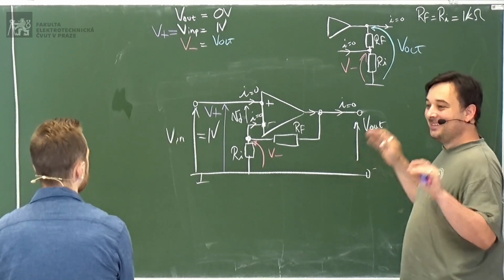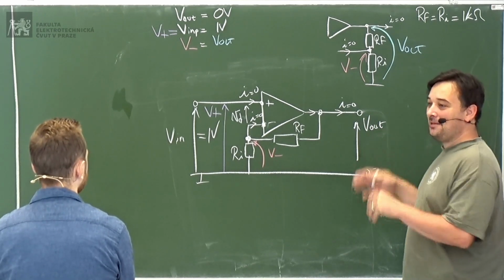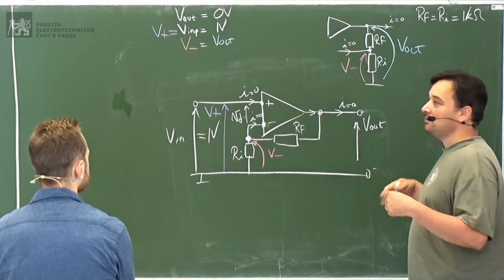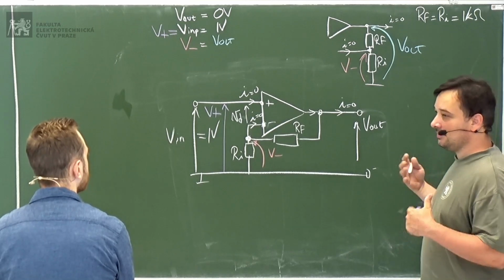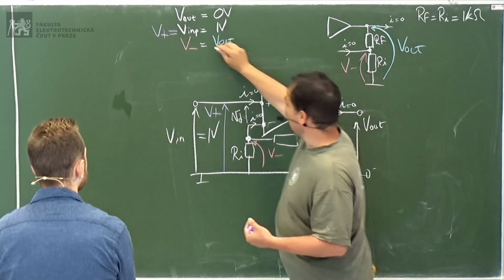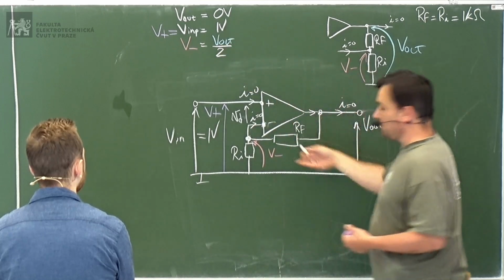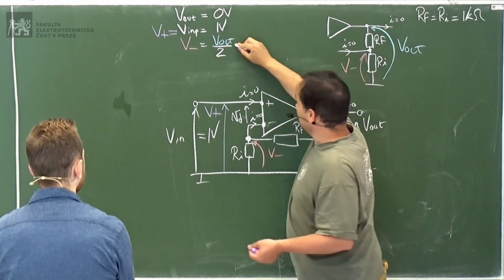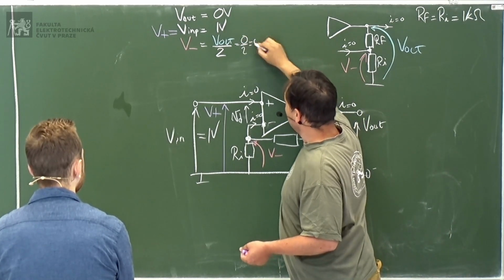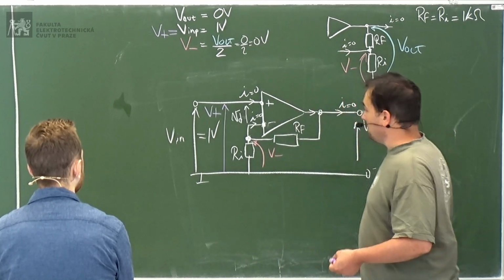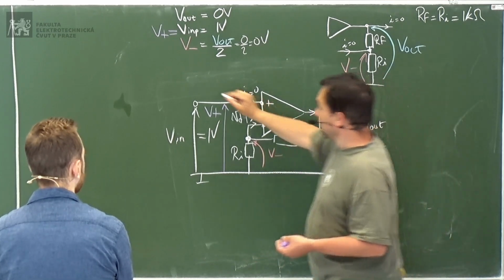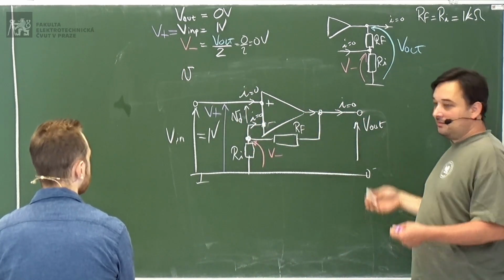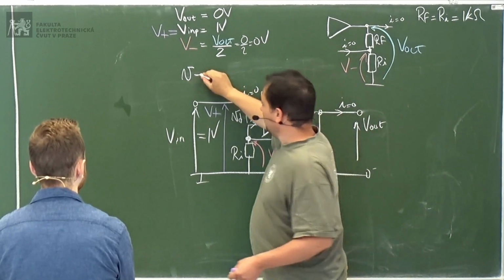Yeah, you're jumping. I just want to understand why we arrive at the final gain and so on, but especially I want to explain how the system works, okay? So this is V out divided by 2, because we have these two resistances. In this case, the output is 0, so 0 divided by 2 is 0 volt, okay? It's divided by 2 because RF and RI are equal, otherwise it would be different. The voltage divider rule says it would be half.